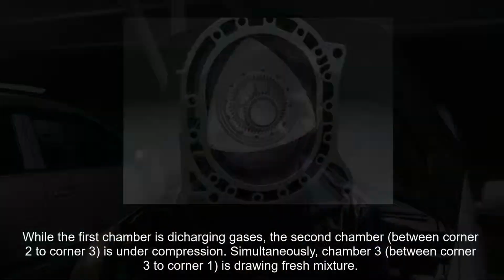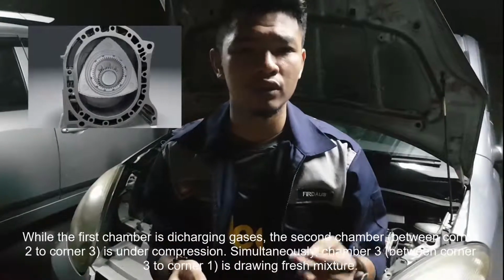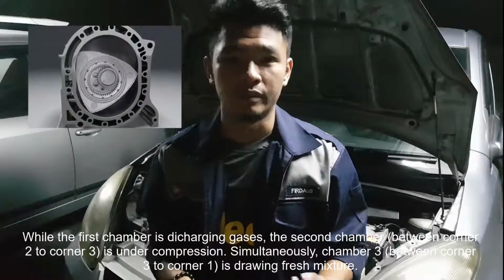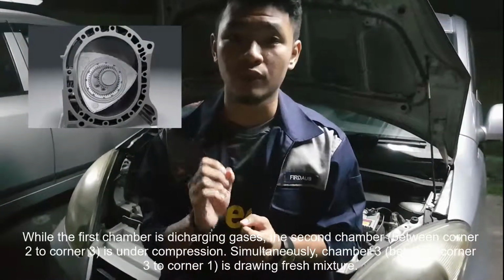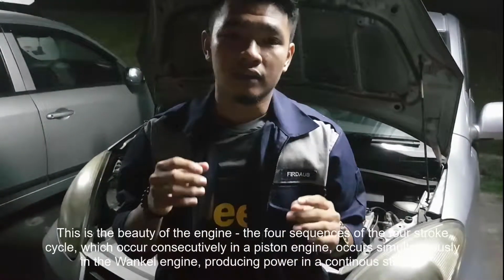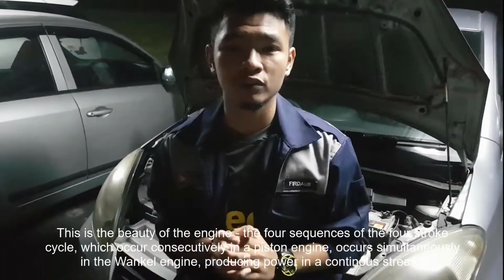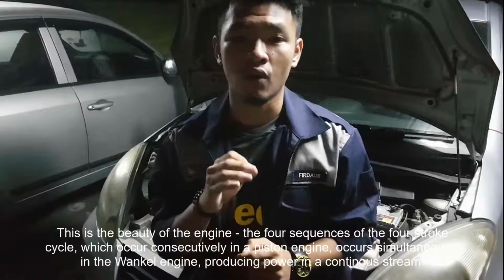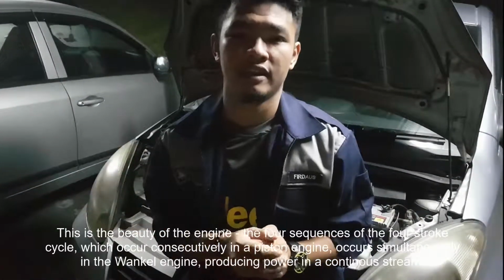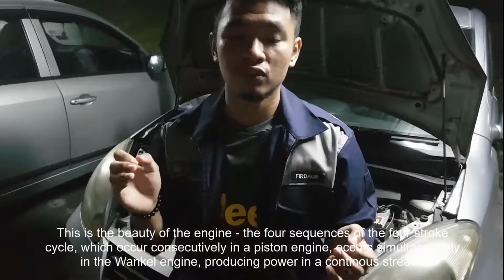repeating this cycle. While the first chamber is discharging gases, the second chamber between corner 2 to corner 3 is under compression. Simultaneously, chamber 3, which is between corner 3 to corner 1, is drawing fresh mixture. This is the beauty of the engine. The 4 strokes of the 4-stroke cycle, which occur consecutively in a piston engine, occur simultaneously in the Wankel engine, producing power in a continuous stream.